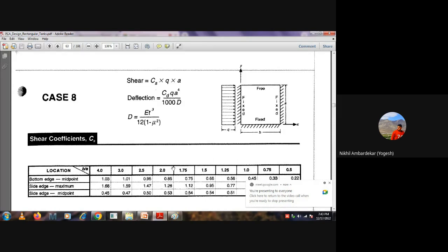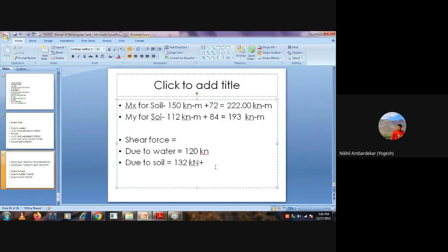What is the value of the surcharge shear force? Kilonewton. No, what is the value? I don't remember. What is the maximum? Q is equal to 10. Correct. Q is equal to 10. What is the maximum shear force? 74. Yes, sir. I think at first instant I considered 55. So 74. Okay, that is also kilonewton.